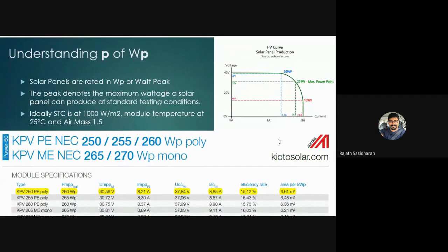That's also important because there is a spectrum, and we have an air density and the incident angle. So they consider air mass to be 1.5 and do the testing at the panel. When they do this testing, they will get the below mentioned results. So let's see. Let's start with the VOC. VOC means open circuit voltage.